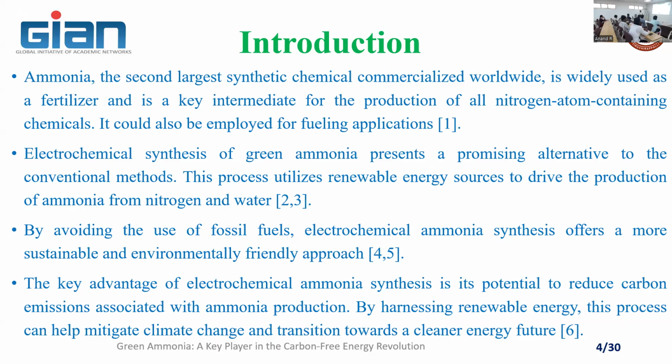Yesterday we saw some of the green methodology, which I spoke about, and he also mentioned in his lecture: the green method of producing ammonia keeps the Haber-Bosch, with only one modification, avoiding steam methane reforming. We electrolyze water into hydrogen, and nitrogen comes through, I can say, membrane processing or an absorption method, where nitrogen and some oxygen are separated out. Nitrogen can be used in the Haber-Bosch reactor. In that method, we are eliminating carbon dioxide completely. The ammonia we get using electrolysis along with the Haber-Bosch reactor is free from carbon. So that's why it's called green ammonia.